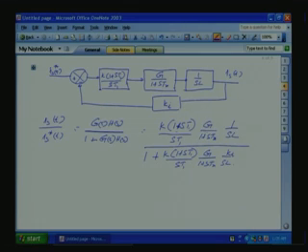The moment you have the converter of the type 1 plus S TR, it will give a delay. This delay can be cancelled by this one, so the response can be faster. So, let us make T1 equal to TR, so that the large lag element, the delay element due to this converter 1 plus S TR, can be cancelled by this lead element from our PI control. So, let us take T1 equal to TR. If we use it, we can cancel these two. Okay. So, the system becomes simpler.